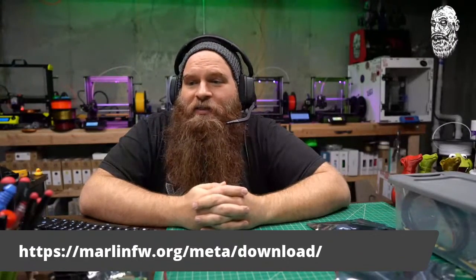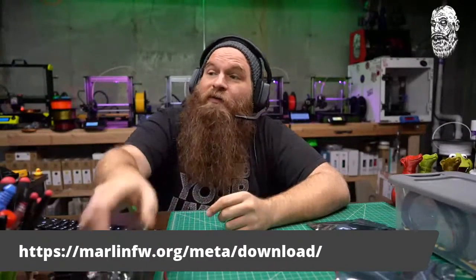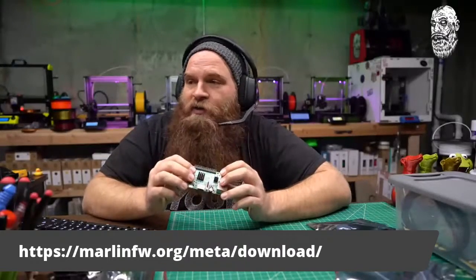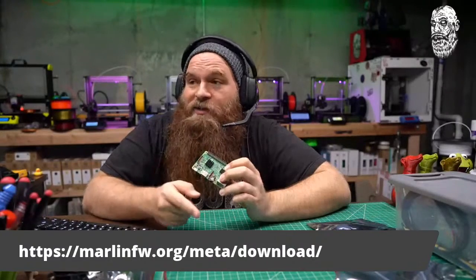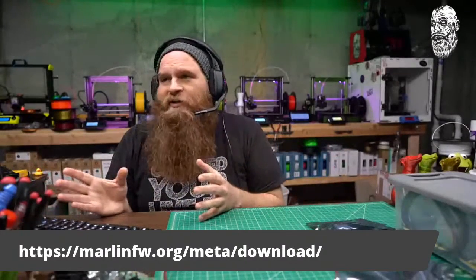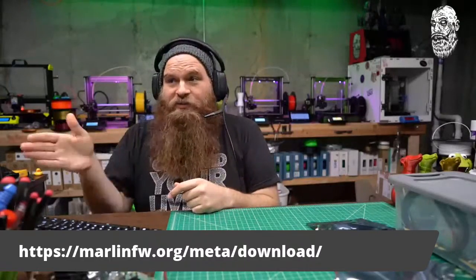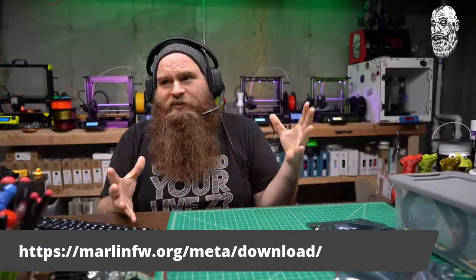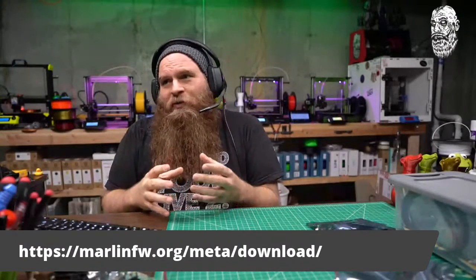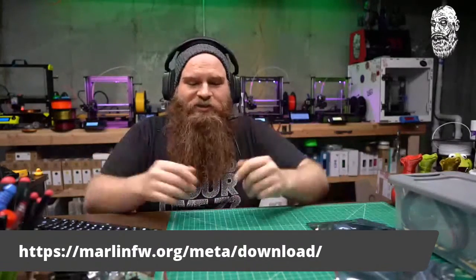Is there any benefit to adding Klipper? There's always a benefit in using Klipper just because the MCU is much more powerful. The processing power is greater, and the way it works is better. It's doing all of the calculations on chip, sending them as needed to the board. So there should never be what's called a buffer overrun, where too many processes are being sent to the board, it gets filled up, and then it can't send, and you get a stutter. You'll see the printer slow down, or if it does a curve, you see it go choppy. That usually just means it sent too many things and the well is too full. Things are coming out, and it's like, hold on, I've got to catch up. And it starts getting choppy.